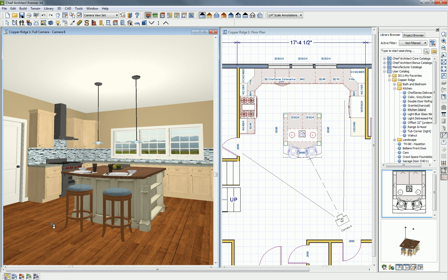And what that allows us to do is to apply a material to a component like just this little drawer, or to an object. If I click on this object, it does the entire cabinet, or to everything in this entire room. So if I click on this cabinet, it's going to change all the cabinets in this room. And if I go into floor, it does all of them on the floor and all of them on the plan. So we have a lot of control on how we can add a given color material in a plan to make it quick and efficient. Okay.